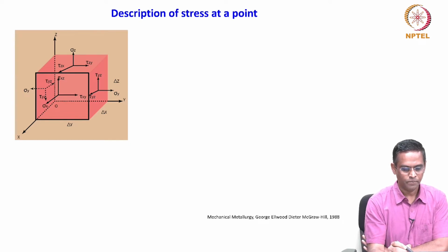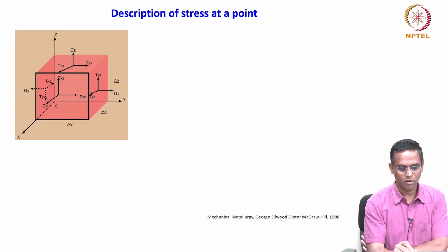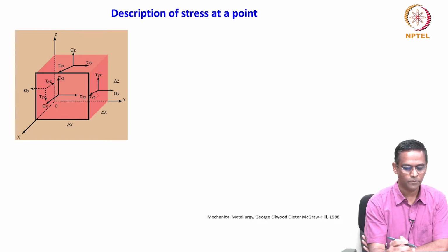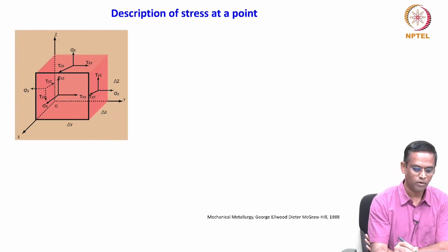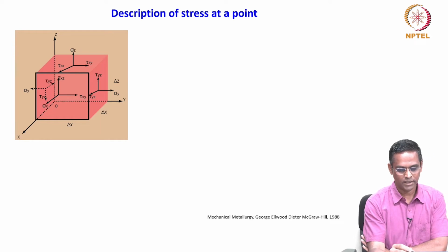It is understood that a normal stress acts perpendicular to its plane. So, sigma y means a normal stress acting perpendicular to the y plane. On the other hand, for shear stresses you need two subscripts, because we need to know first of all where the shear stress lies.